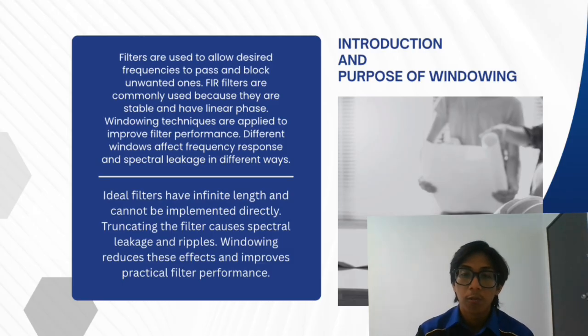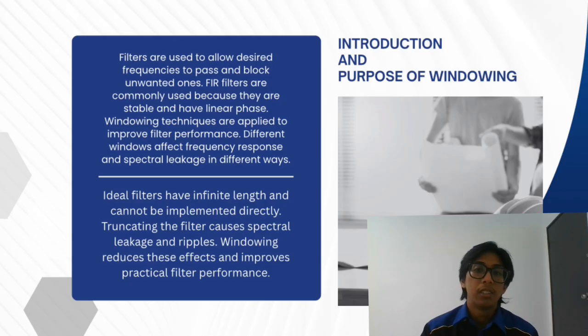So for the purpose of windowing, ideal filters have infinite length and cannot be implemented directly. Truncating the filter will cause spectral leakage and also ripples. Windowing will reduce these effects and will improve practical filter performance.